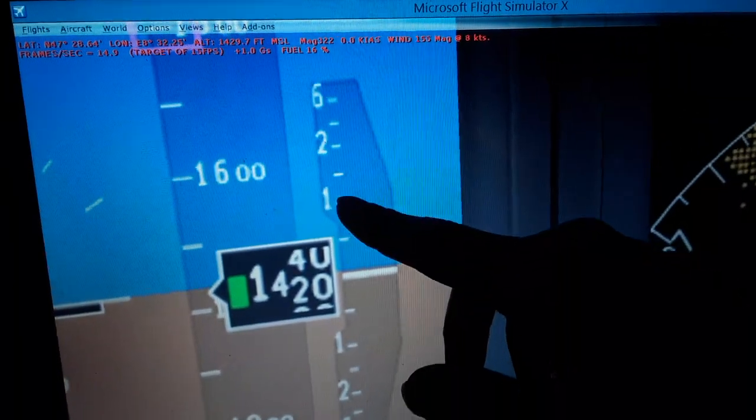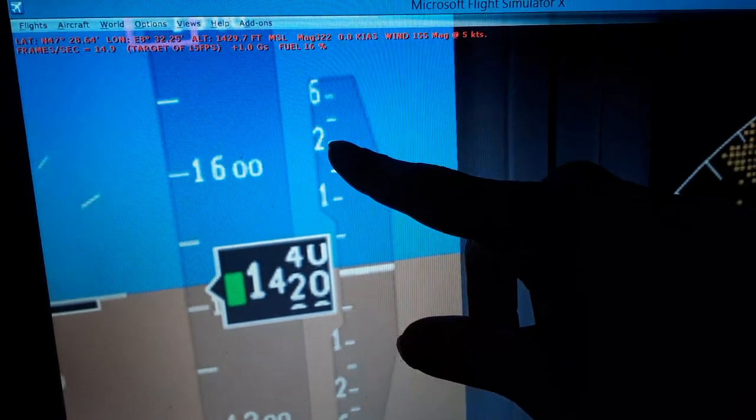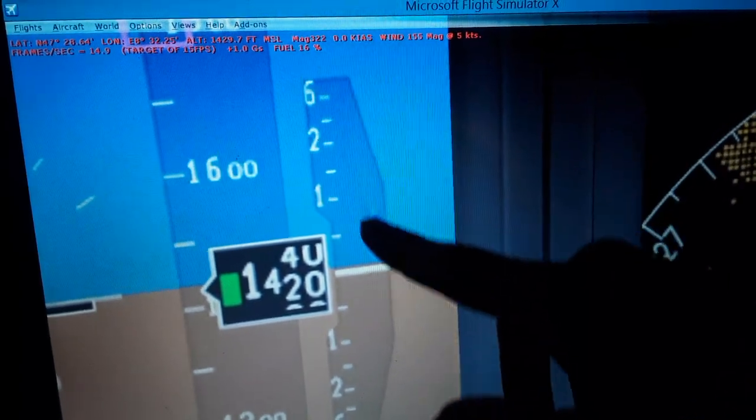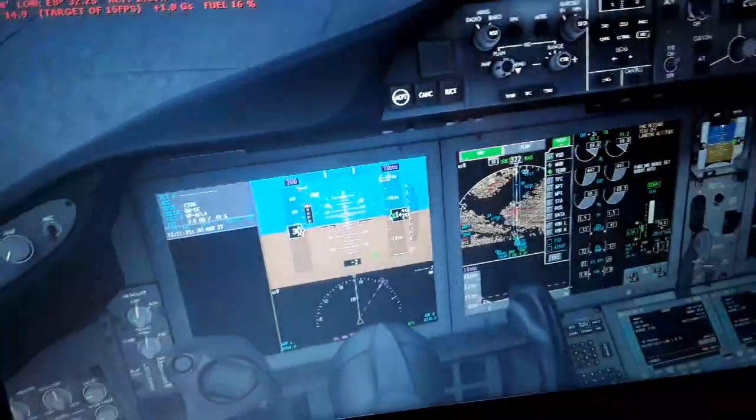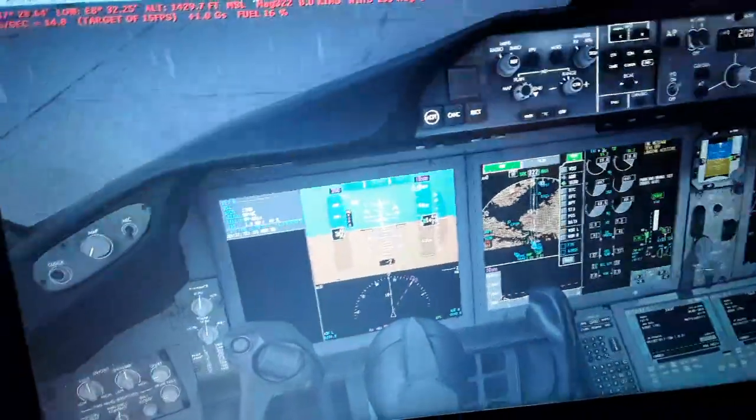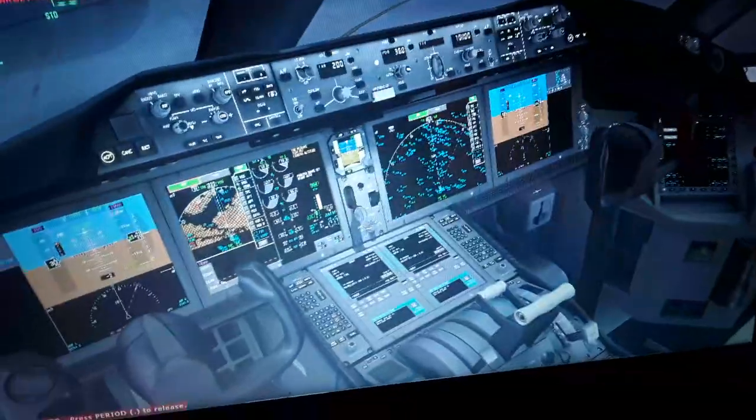So it's going to give us 500, 1,000, 1,500, 2,000, 3,000, 6,000 feet as the tick marks displayed for climb or descent, how fast we climb or descend the aircraft. We need to pay attention to that mostly, to know whether we climb or descend, or the altitude difference.